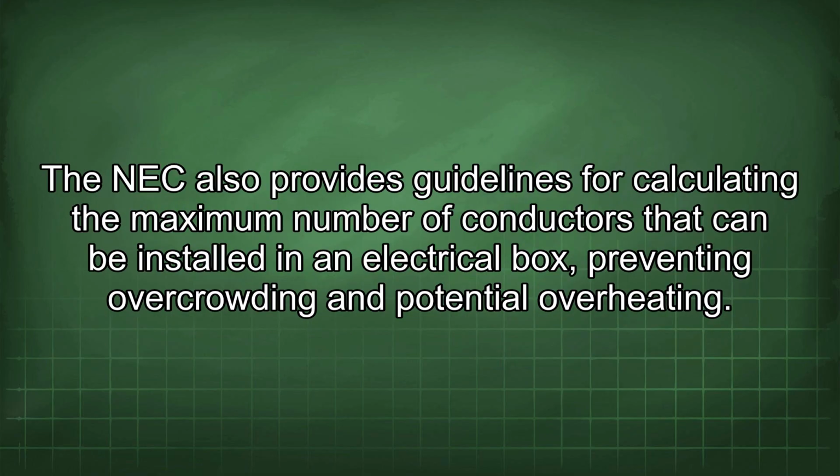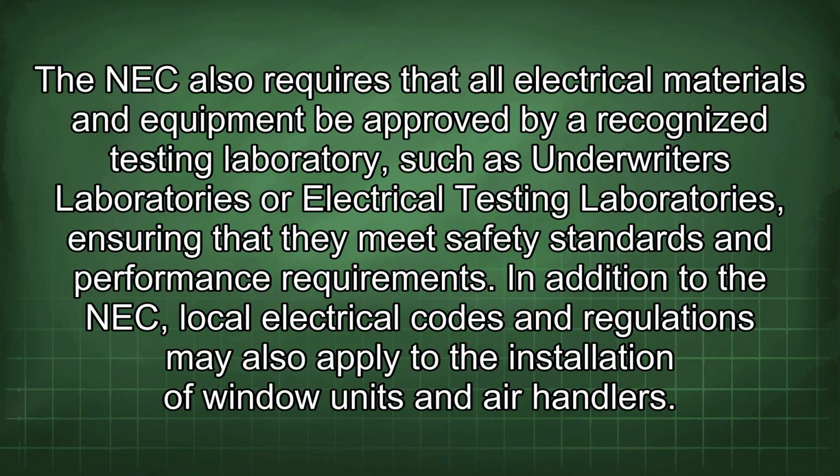The NEC also provides guidelines for calculating the maximum number of conductors that can be installed in an electrical box, preventing overcrowding and potential overheating. The NEC also requires that all electrical materials and equipment be approved by a recognized testing laboratory, such as Underwriters Laboratories or Electrical Testing Laboratories, ensuring that they meet safety standards and performance requirements.